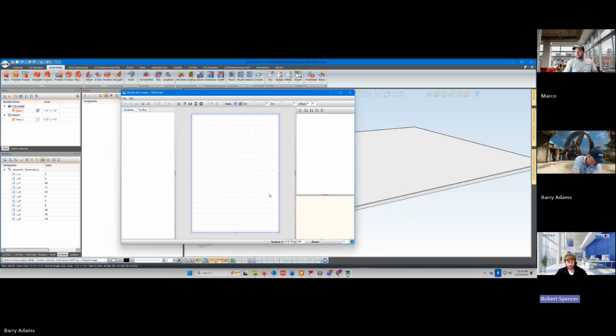So the sketch will drive these variables. When you apply the element to your grid, in the background it's going to be coming up with how many edges are counted, 3, 4, or 5, or whatever. And then it's going to use the IX and IY values that are returned and measured from that sketch. And it's going to feed them in the background into the variable list of this variant. And that's how the shape is going to be correct for that grid area. So it's all happening in the background.